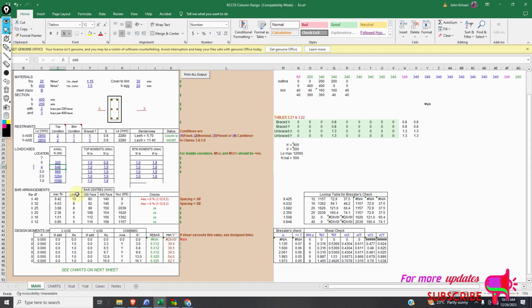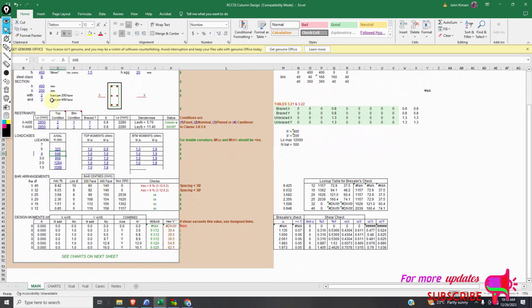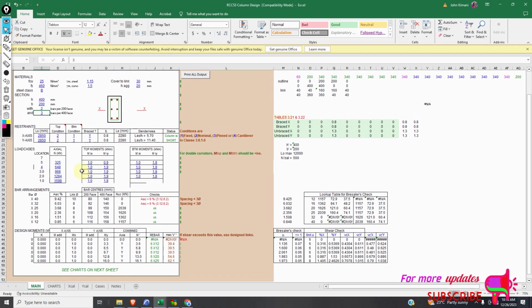So you can see the design that we are getting if we use this, because we still want to minimize this column. So we are getting such a design. If we increase this one to 25, we're still getting the same thing. So let's just try to minimize it as much as we can. Because now that the other one is preliminary sizing, we know where it should be around. We have to increase this one now to 3 for the design to pass. Get maybe what we need, right?